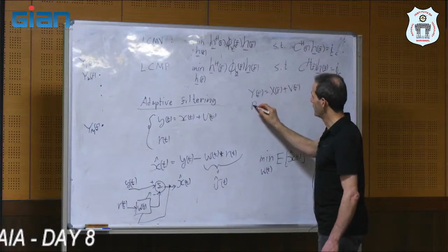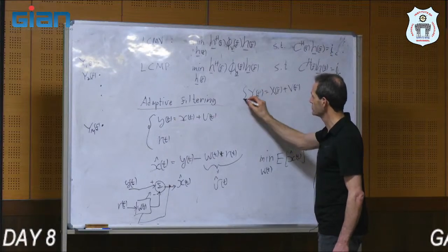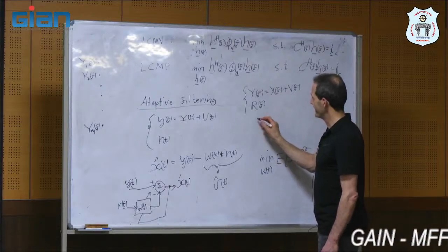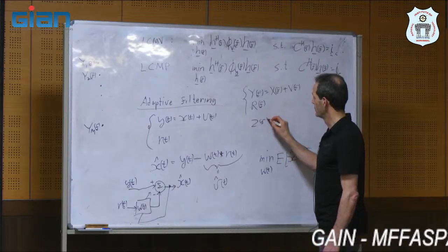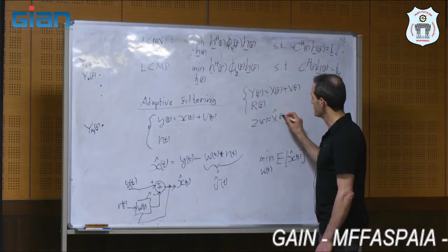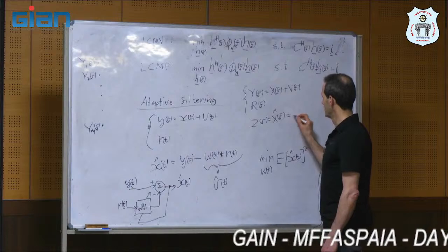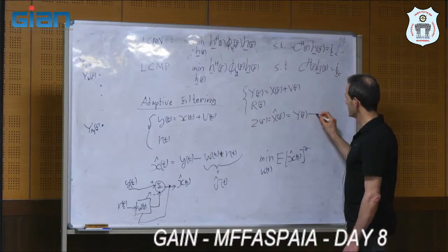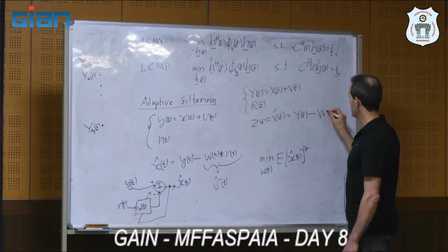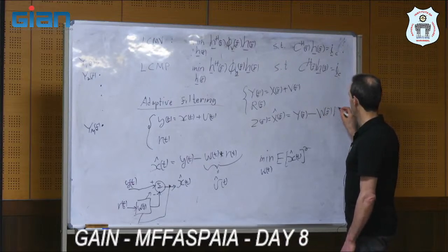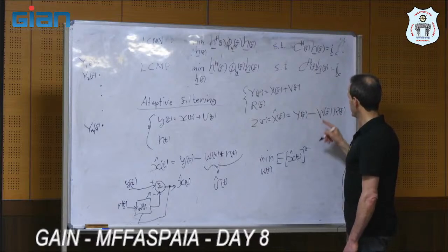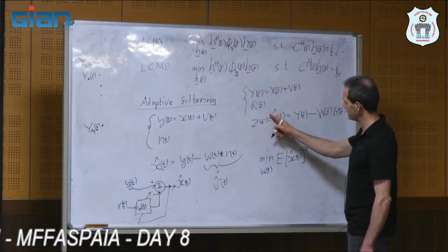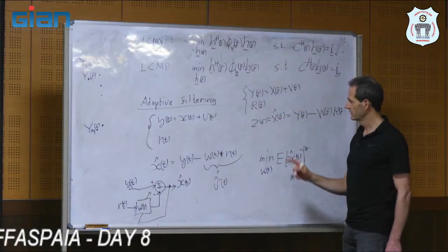And we have our reference channel in the frequency domain. So we have two channels. And then we try to find an estimate, ZF, which is an estimate of XF for each frequency, by taking YF and subtracting a filter, WF, that multiplies RF. And we need to find the optimal W, by minimizing the variance of ZF.